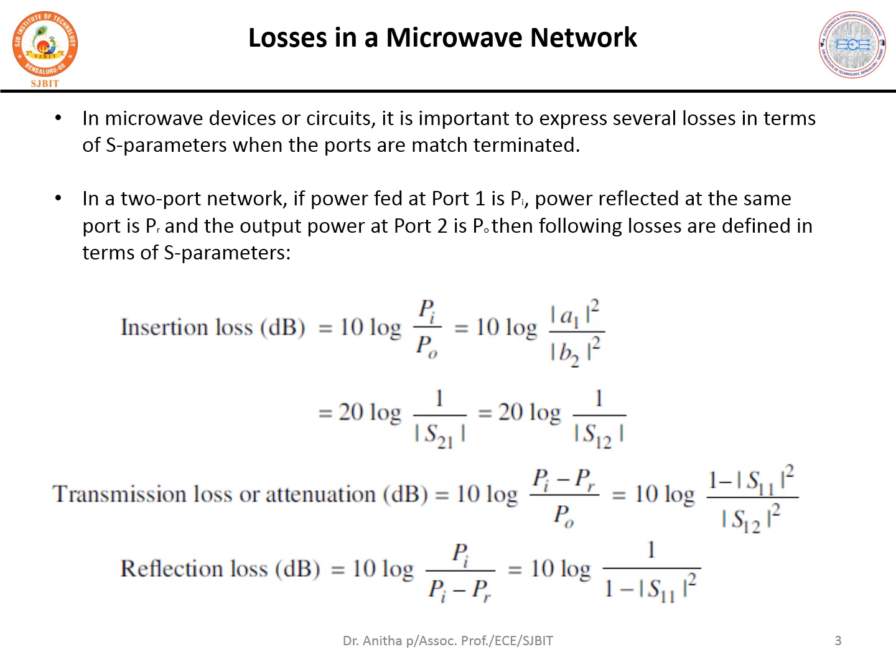All these values are expressed in decibels and they are expressed in S parameters also. Coming to the first loss, we call it insertion loss. It is nothing but the ratio of input power to output power. Let us consider I had given 10 watts of input power, and only 6 watts has reached the output. The Pi to P0 ratio, that is 10 divided by 6, will give you the insertion loss, the amount of loss which has occurred in the device, in the network.